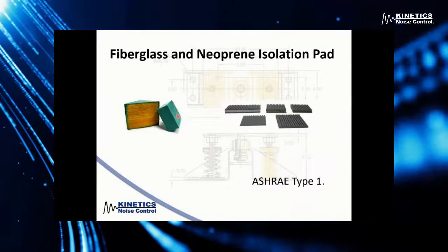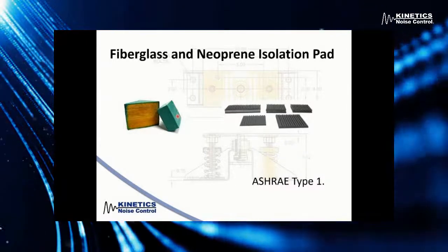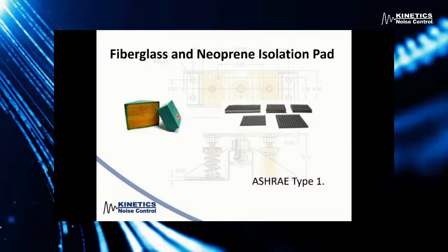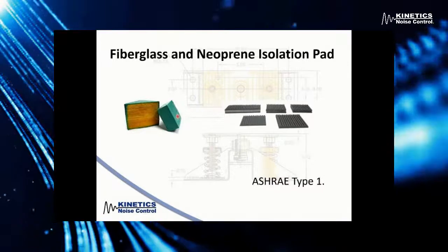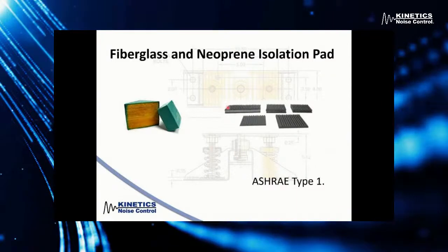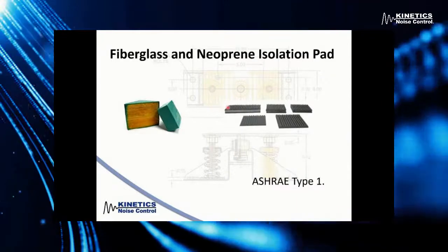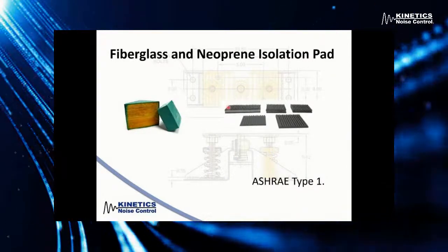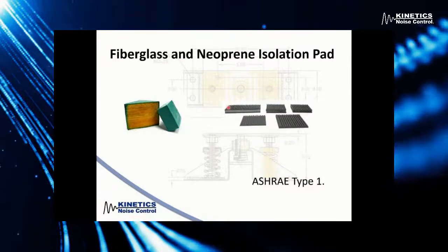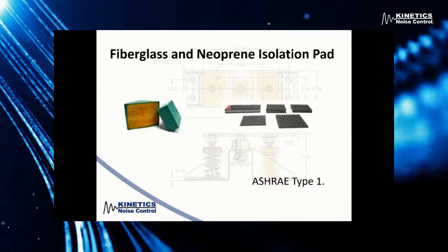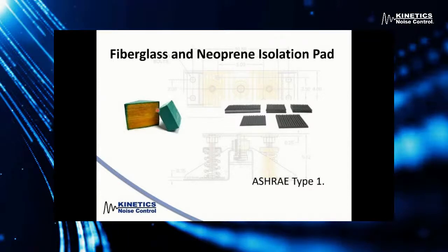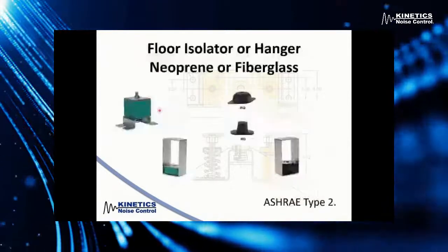The very reason we park our campers and RVs and we cover the tires up is so the sun doesn't dry rot the rubber. Same thing with neoprene. That's going to break down from UV. And then temperature can affect rubber and neoprene. In Calgary, for instance, in the middle of the wintertime, a neoprene rubber isolator is rock hard. It's like a hockey puck, and it's not going to deflect. So the vibration is going to travel right through the hockey puck, as it were, whereas fiberglass is not going to be affected by temperature.